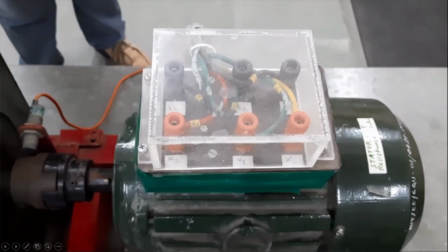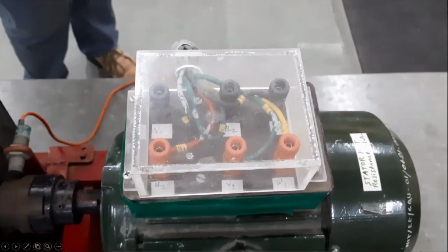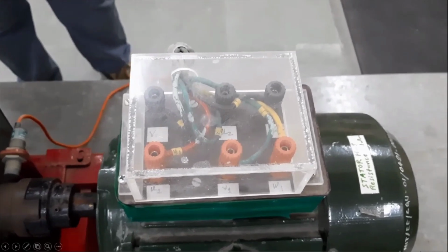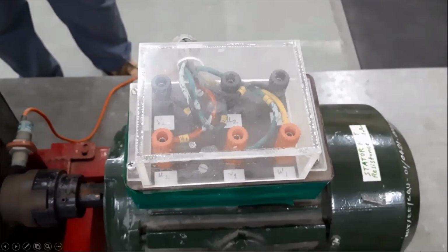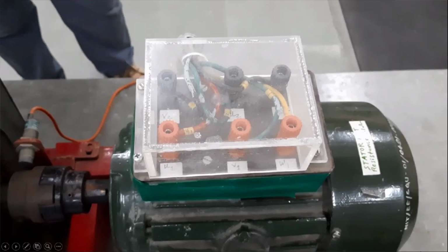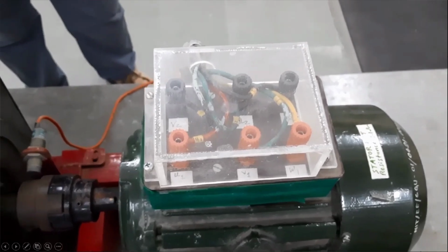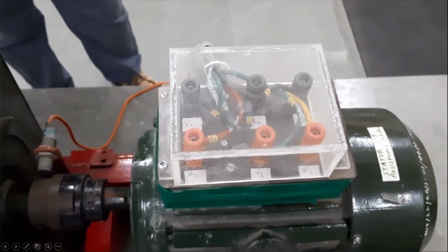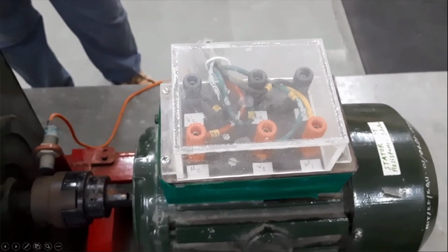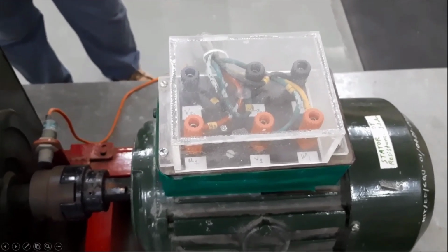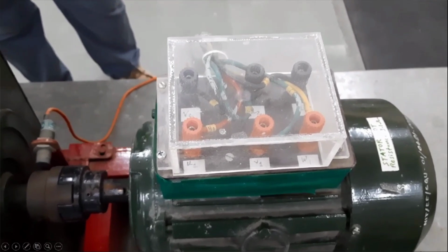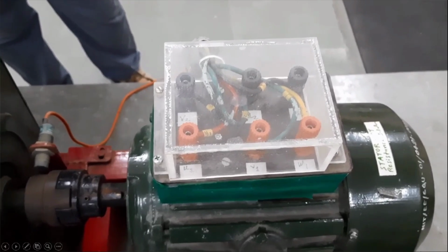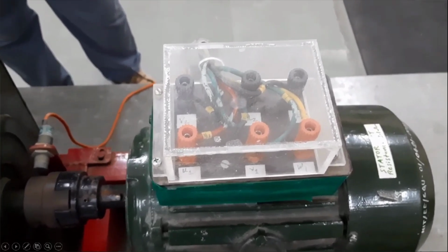The reason behind that is, our nominal 3-phase supply in India is 400 volt line to line. Now when we see the delta connection, you are very well aware that in delta connection, line voltage is the same as the phase voltage, and we are concerned with the phase voltage that we would like to apply to the motor. So initially, if the motor is in delta connection, then the phase voltage of the motor will also be 400 volt, and the motor will start drawing enormous current. That enormous current will affect the other apparatus connected on the same supply, and they will face a voltage dip.